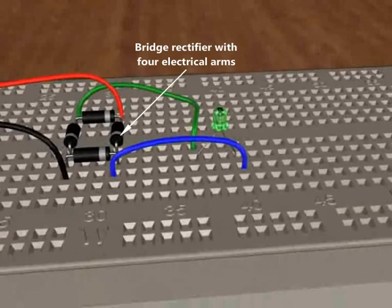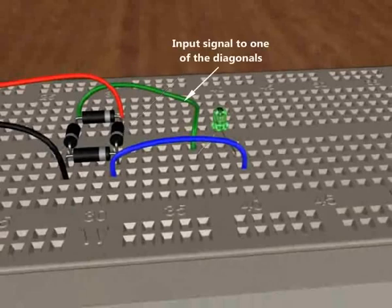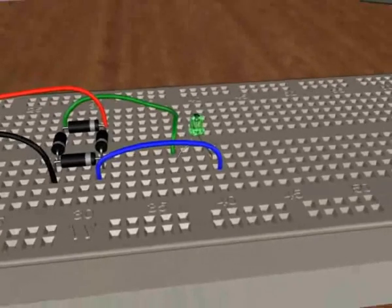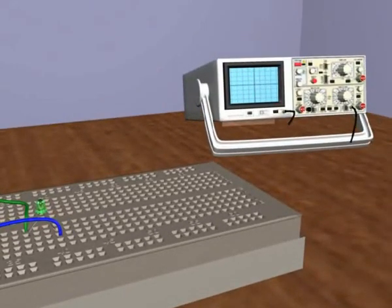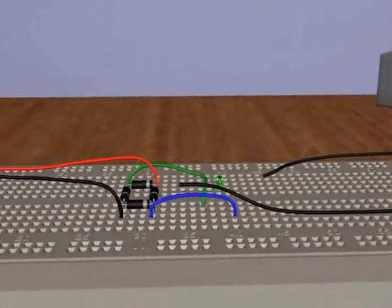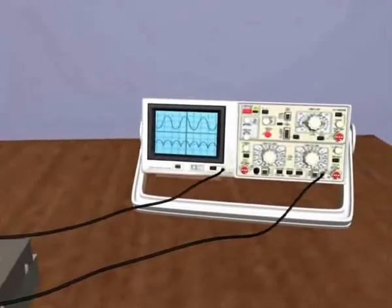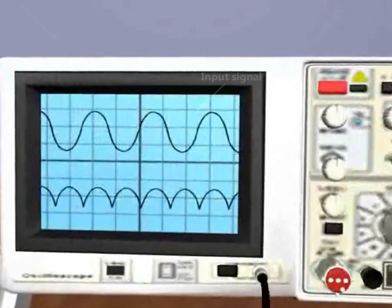Bridge rectifier with 4 electrical arms. Input signal to one of the diagonals. Output signal from the other diagonal. The input signal and the rectifier output signal are shown in the CRO display.